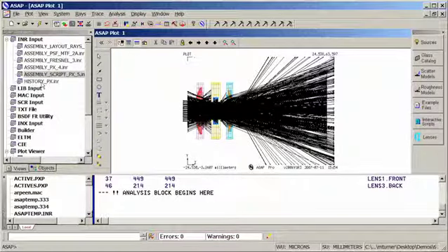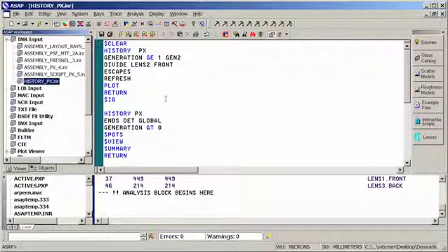So what I might want to do again is to use my Path Explorer, but in this case, let's take a look at how we do it in terms of the scripting environment. In this particular case, what I want to do is look at all of the rays that make it to the detector, and also get an idea of where all of the rays that didn't make it to the detector exited out of the system, at what surface within my design. This is an example of Path Explorer commands within ASAP. This first set of commands is for the previous example where we looked at the Fresnel reflections off the front surface of the second optical component.